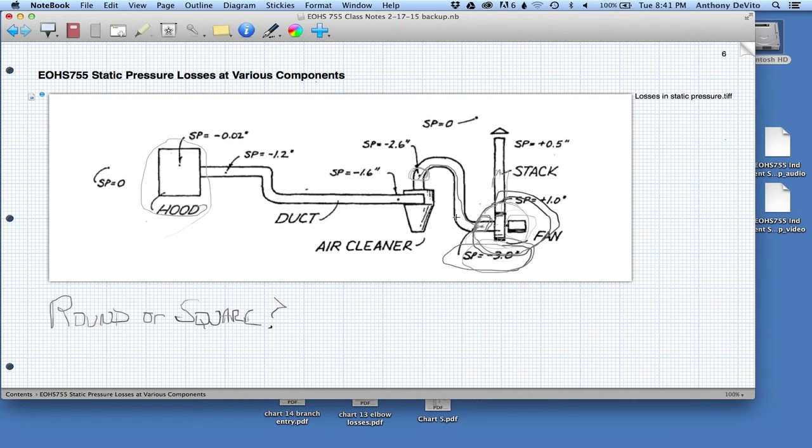What do you think it is about this ductwork that caused us to lose a significant amount of suction between the fan and this point right here? You can see in that drawing, right? Curves, elbows. We have friction in the ductwork, but when you get to these elbows, it really messes things up, because the air bangs against the wall and you lose a lot of energy going around curves. We've got 1, 2, 3 of them to get to this filter. So we lost a lot of energy to these curves.